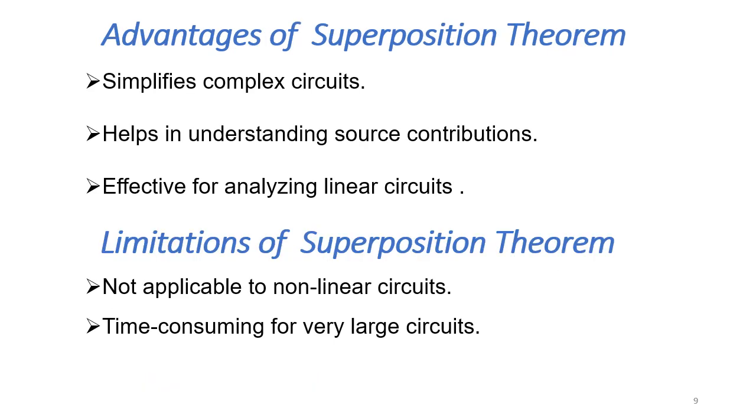Next, advantages of superposition theorem. It simplifies complex circuits. It is helpful for understanding source contributions, and it is effective for analyzing linear circuits. Then what are its limitations? It is not applicable to non-linear circuits, and if the circuit is large, then it is a time consuming process.